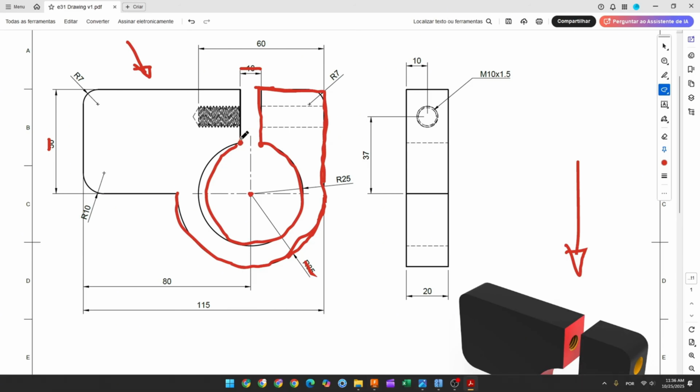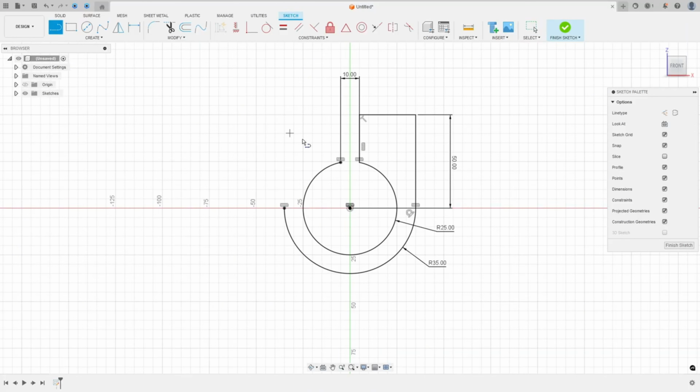Now on the other side here, we'll create a line and create this sketch here. Okay, the distance between this line and the midpoint is 8 millimeters, okay? So select the line, click at this point, make a line here.